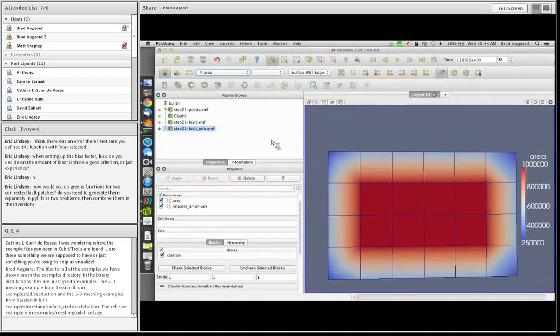And then you could combine the output from those two, so instead of getting the responses from one file, you get the responses from two different files, and then you do the inversion by combining those two into a single inversion. So you can generate your greens functions across a number of simulations for different faults, and then take your Python script.